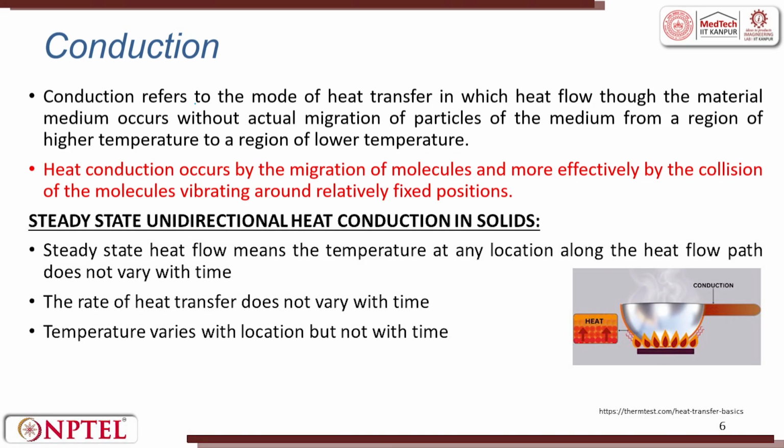Conduction refers to the mode of heat transfer in which heat flows through a material medium without actual migration of particles of the medium, from a higher region to a lower region. Conduction occurs by the migration of molecules and more effectively by the collision of the molecules vibrating around relatively fixed positions.